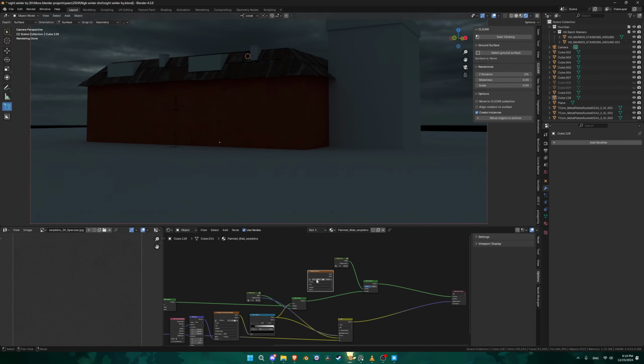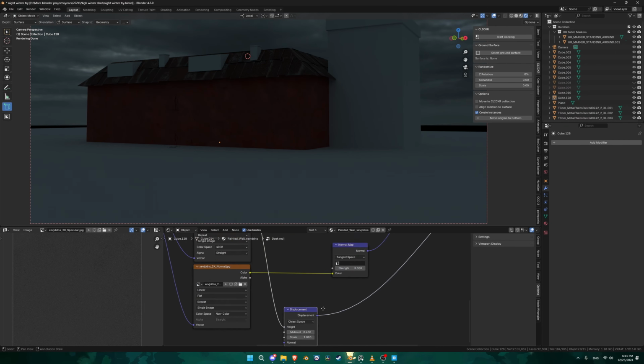For the third layer, I'm going to create an image texture and make it 2K in size and use that as a factor instead, because this time we're going to paint it. I'm going to call it dark red and desaturate it and reduce the value by a lot, maybe 0.4. And now bring in a decent brush texture that you're going to use to paint. You can find a lot of nice brushes on Quixel Bridge.